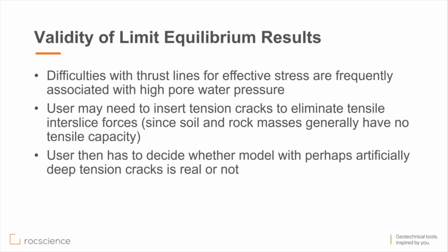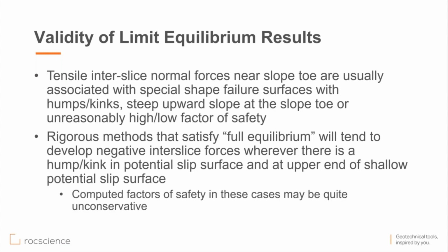But sometimes in doing so, it makes the problem unrealistic. Let me add that tension cracks are not a panacea to every problem of the rigorous methods. So you may have to judge whether it is good enough, or whether adding tension cracks really improves the solution.